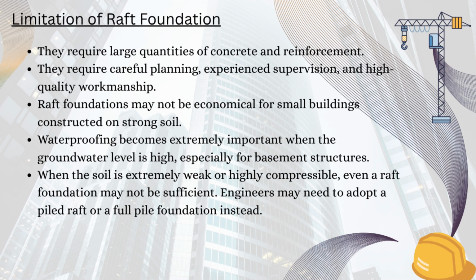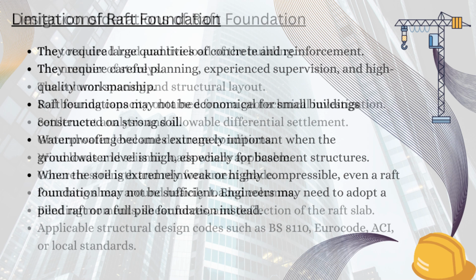Raft foundations may not be economical for small buildings constructed on strong soil, where isolated footings can provide the same performance at a much lower cost. Waterproofing becomes extremely important when the groundwater level is high, especially for basement structures. Finally, when the soil is extremely weak or highly compressible, even a raft foundation may not be sufficient, and engineers may need to adopt a piled raft or a full pile foundation instead.